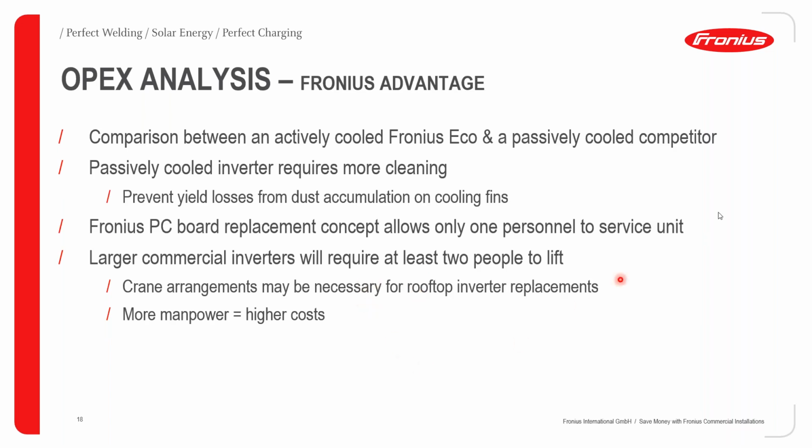So in terms of the Fronius advantage as far as OPEX is concerned, all our inverters are actively cooled, and we are going to be comparing with a passively cooled competitor inverter. But when you're talking about a passively cooled inverter, you require more maintenance or service efforts. This includes cleaning of the cooling fins to prevent yield losses from accumulation of dust on the fins themselves.